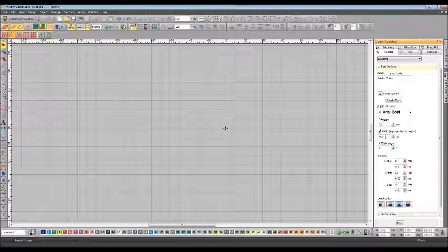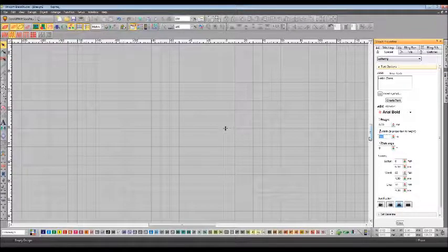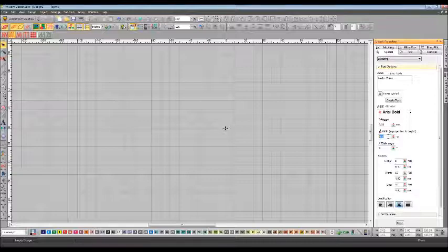Width in proportion to height: 100% of the width is 100% of the letter. If you want to condense it, we can make it condensed. You can set that up now, or you can do it later, it doesn't matter. If you want this to be italicized, what angle do you like it at? Letter spacing, word spacing, line spacing, pretty straightforward. And you want it left or center justified. Most often, center justified is fine.